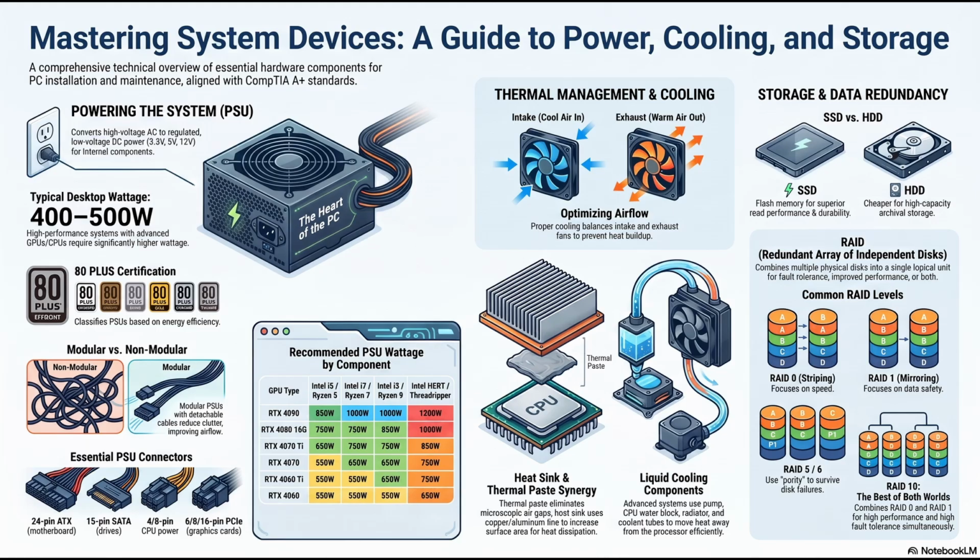If you take two identical sticks of RAM matched in speed and capacity and install them into specific color-coded slots, the motherboard's memory controller activates dual-channel mode. It essentially opens a second door. It binds those two separate physical sticks into a single logical block of memory and utilizes two separate 64-bit pathways simultaneously. You have doubled the total data bandwidth instantly. High-end workstation motherboards support quad-channel memory, utilizing 4 synchronized sticks to provide massive data pipelines for tasks like real-time 8K video editing.